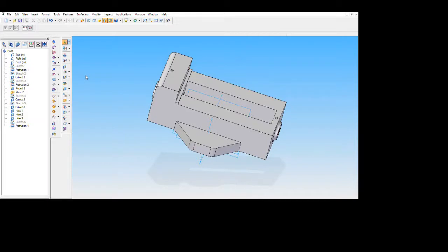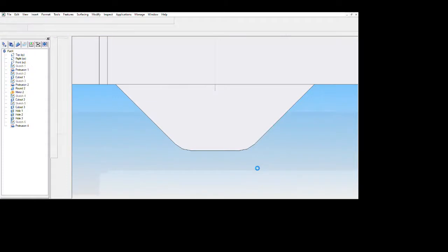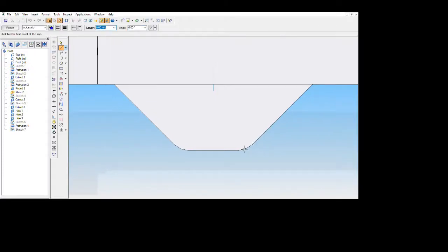Now the cutout should be made in this part that is protruded. Select the sketch option, select this surface. Now draw a circle using this axis as the center plane, of any diameter at the start, and give the diameter as 16 because the radius that is given is 8. The diameter will be 16.